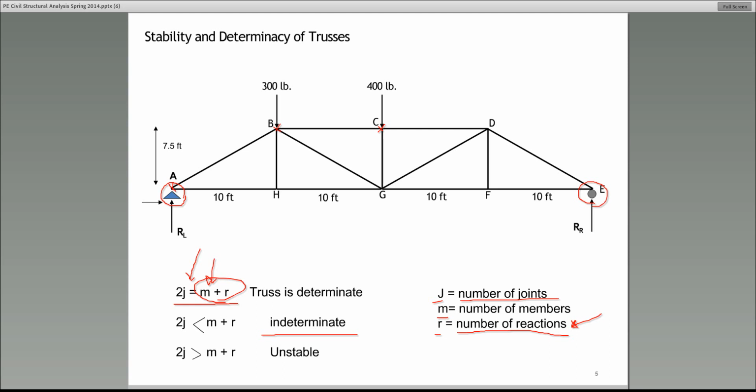Stephen Marzi says sum of fy, fx at each point. Yeah, that's correct. Absolutely. Excellent. Are you a structural engineer? Here, 2 times j, guys. See, at each joint we have 2 equations of equilibrium. Because each joint, for example, C, D, B, whichever joint, we consider to be a hinge. And all we have to do is satisfy 2 equations. Summation of forces in the x direction equal to 0, summation of forces in the y direction equal to 0. So as Stephen says, here's what happens.